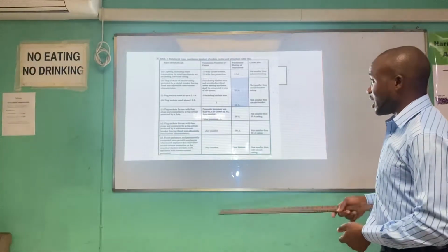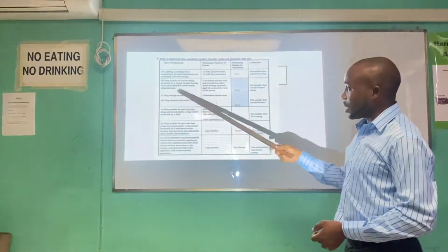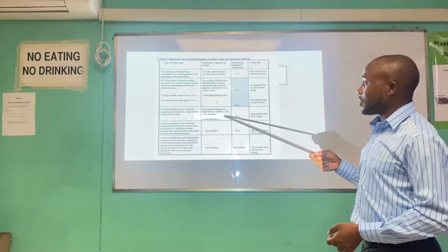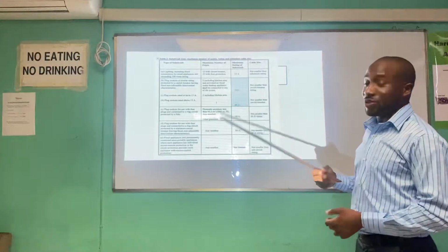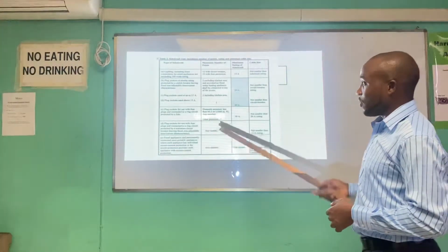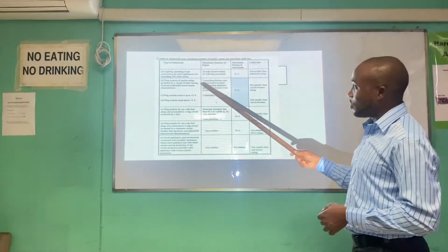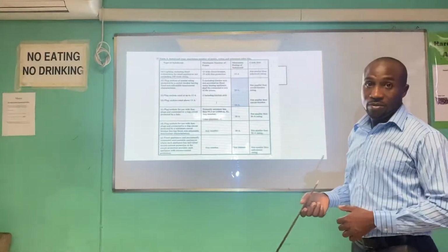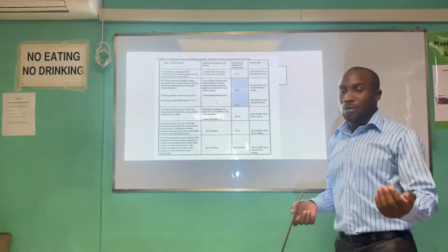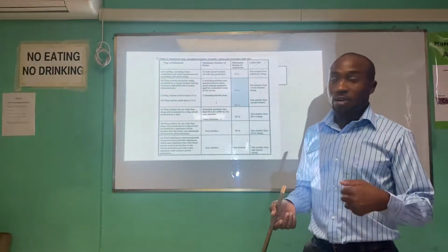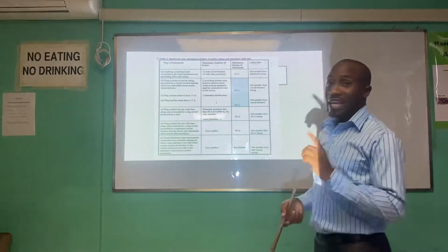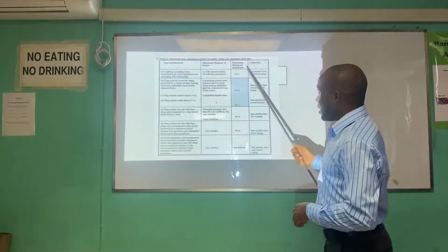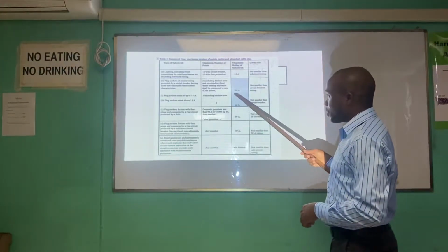Right, so they provide this particular table. I will send the presentation so you will have this table and be able to actually see it. I know it might not be so clear now, but for a plug circuit, it's saying that you can add up to five plugs excluding the kitchen area. So if you put plugs in the walkway, in the living room, or in your bedroom, you can have up to 5 plugs on any one circuit. And the maximum rating of this sub-circuit should be 20 amps.